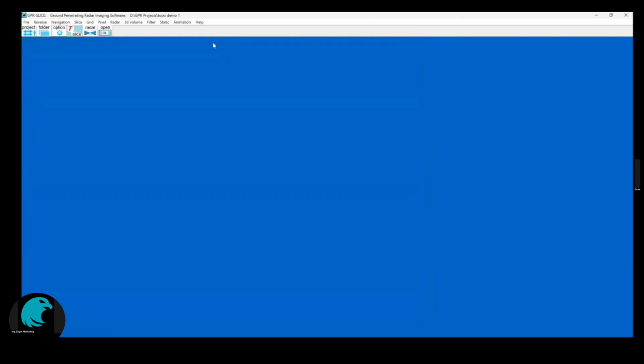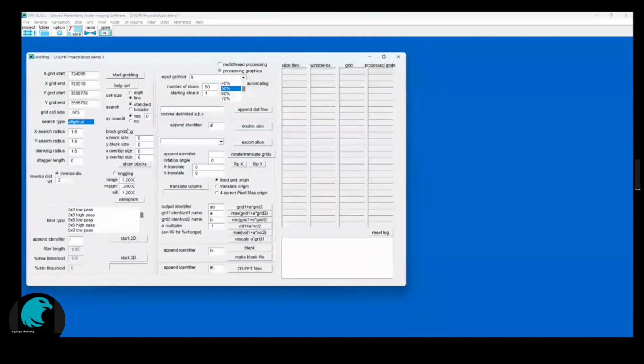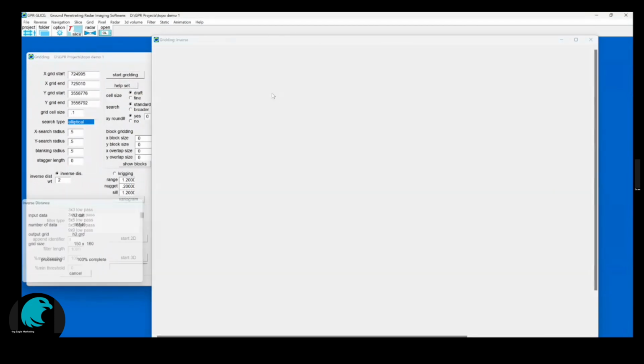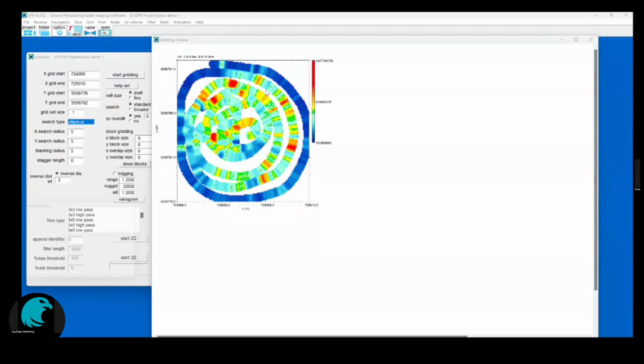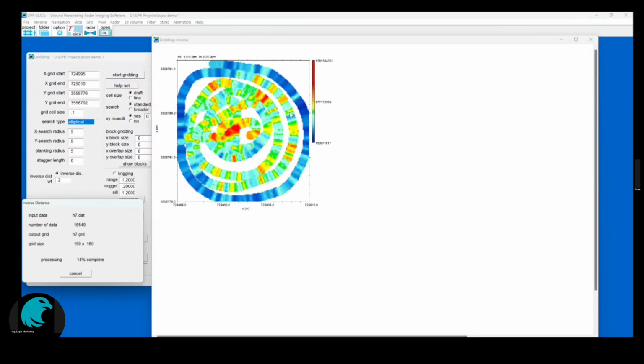Okay, our next step is to do gridding. We're going to come in here and we'll just put this on draft quality. And I'm going to start out with a search radius that's kind of narrow. And you can see what it does. It's using the 0.5 meter search radius on the data on the grid. And we use 10 centimeter pixels. And so you're seeing data like this. I don't think we'd want to create data like this. Kind of looks like DNA readings in a way.